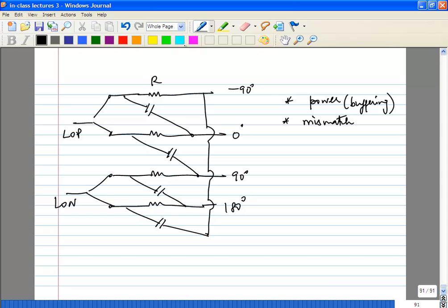Because your RC decides what frequency you're operating at, and if you decrease your C, you become more sensitive to parasitics. You have to keep that in mind. As you go to higher and higher frequencies, this becomes a problem, because both R and C become small first of all. And now you want to make your R as large as possible, so your capacitance becomes really small.